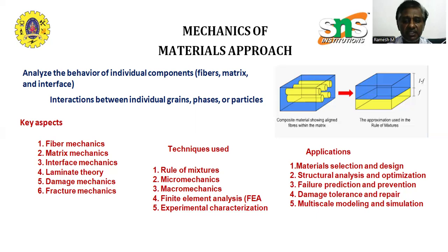Thermal means temperature will be focused on. So thermal conductivity, specific heat and thermal expansion tests will be conducted. And non-destructive evaluation, generally called NDT, here it is evaluation, NDE generally. It's ultrasonic inspection, X-ray, CT, and acoustic emission testing. So these are all things coming under experimental characterization.